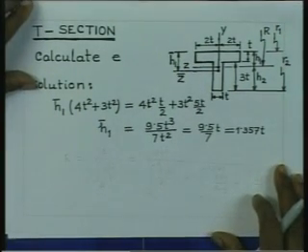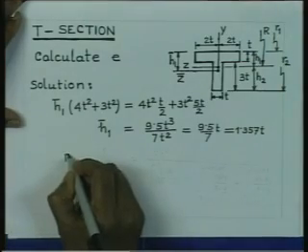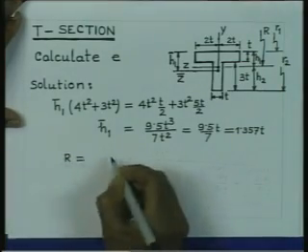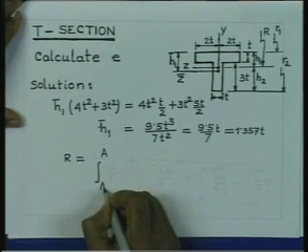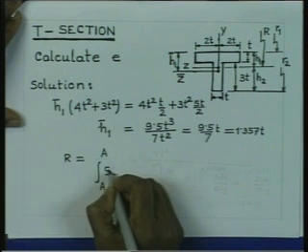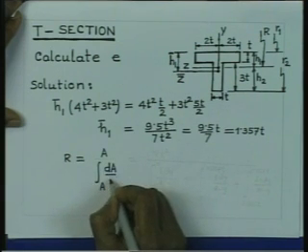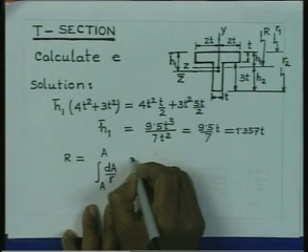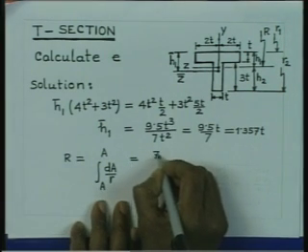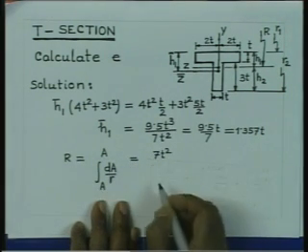In order to calculate this eccentricity, it is necessary to calculate the radius of curvature R of the cross section. The formula for that is here. R is equal to cross sectional area divided by the integral dA by r. The cross sectional area is 7 t square.